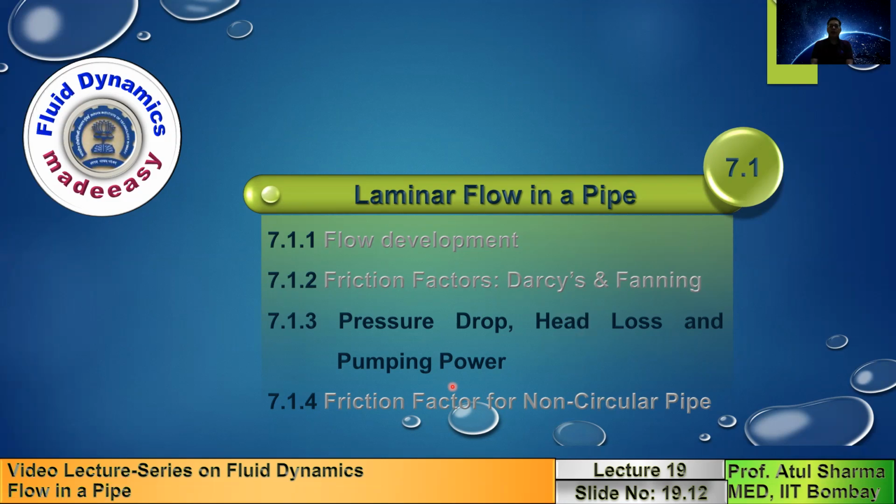For transportation, we need to ensure that at the inlet of the pipe we have provided sufficient pressure, so we commonly use a pump. The pumping power is given by the product of the pressure drop multiplied by the volumetric flow rate. So first I will show you the expression for pressure drop, then head loss will be given by the pressure drop divided by the density rho into g, and the pumping power will be the pressure drop multiplied by the volumetric flow rate.